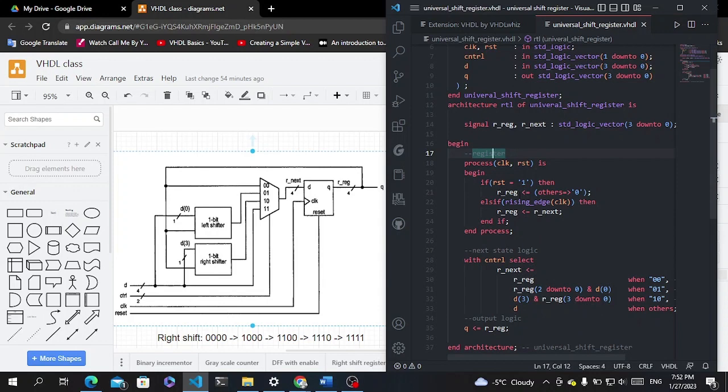like this, which has asynchronous reset, and it's good practice. Your reset should always be active low, so that in a real circuit, if your power goes below a certain point, then your circuit resets, which is what it's supposed to do.